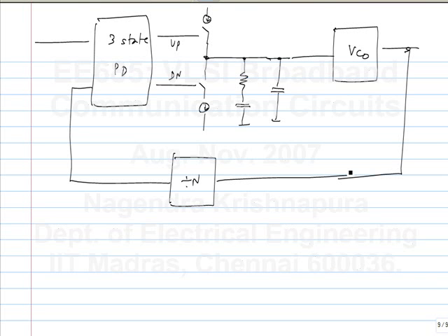So what is the reference feed through? The phase detector output effectively, which you can think of as the current here. The current here is the phase detector output. It's the difference between the currents because of up and currents because of down. That had an average value representing the phase difference and a periodic disturbance that depended on the phase detector design. What is the periodic disturbance in this case?